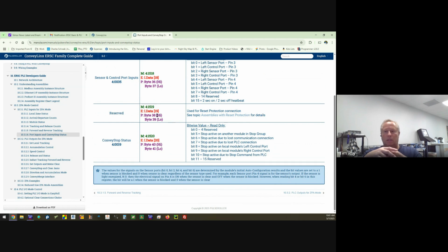The PLC powers up. It's ready to go in a couple seconds. And so it writes to the card, accumulate. Well, the card's still powering up. It's going through its internal tasks. Okay, now I'm done. Open up communications and listen for my neighbors in a PLC.